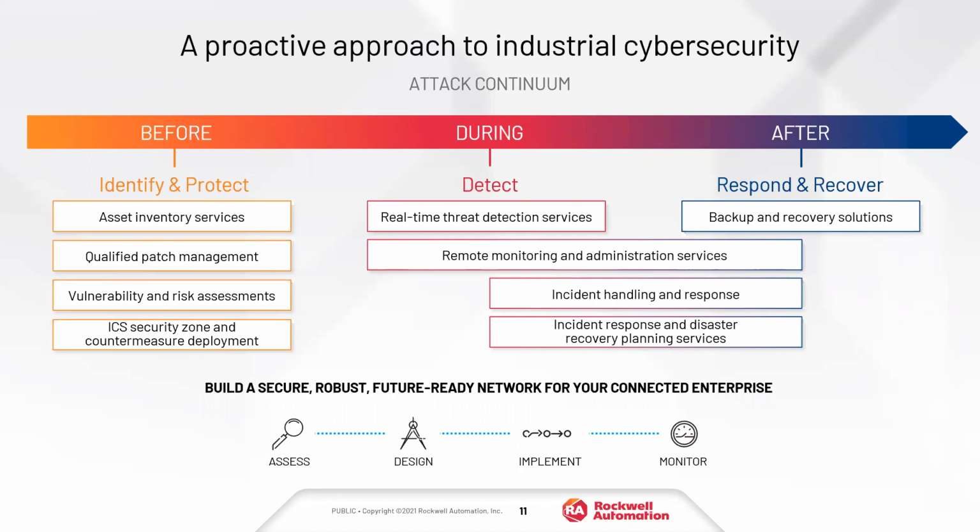When we look at that, you need to understand what happened, what was affected, and follow the plan in place for your recovery. This is also potentially having a team in place that understands what their roles would be as part of that incident response plan. A good example of this is having a comprehensive backup recovery solution. Think of something like FactoryTalk Asset Center. It has the backups of all of your critical assets, the controllers, the HMI, potentially even third party files, stored in one centralized database.